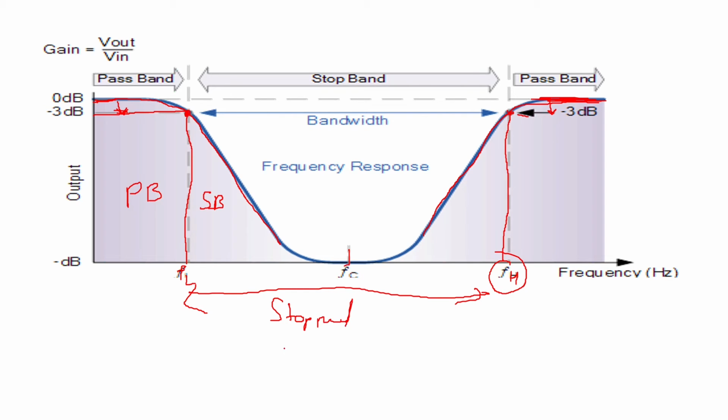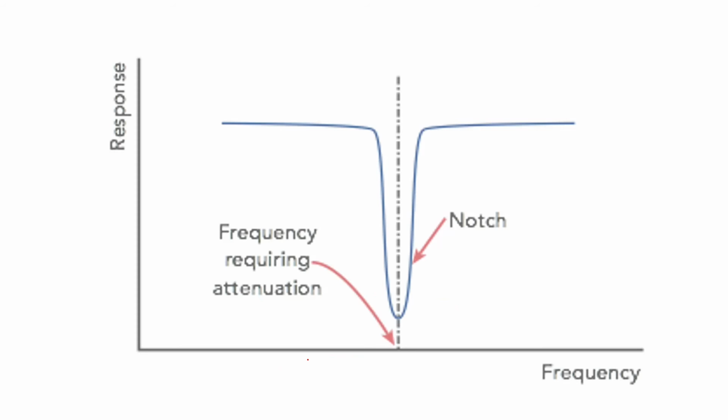They can be attenuated, or they can be rejected. So that is a band of frequencies you're rejecting, and frequencies below FL will be passed, and frequencies above FH will be passed. If you make the band of frequency which you are going to eliminate very narrow, as I am doing here, this is a narrow band of frequency. It can come down to a single frequency also.